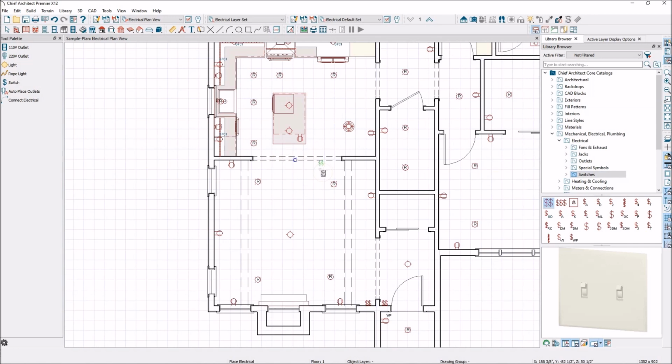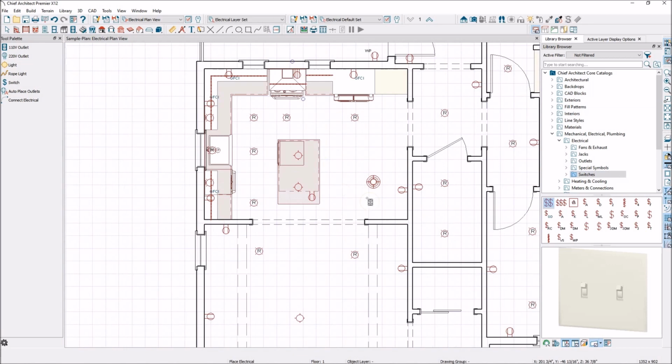And then you probably want to control it from this side of the room too. So if you're coming out of the bedroom, or coming out of the kitchen, and you want to turn on lights here. So let's think about what's happening over here. I probably want a triple one over here, so that I can control these lights, this light, and these lights from there. So let's do that.